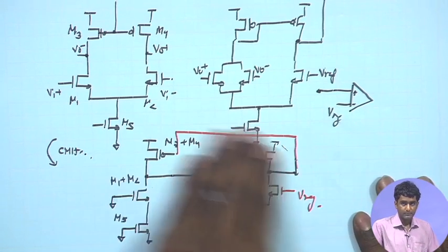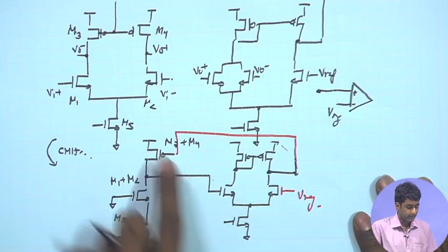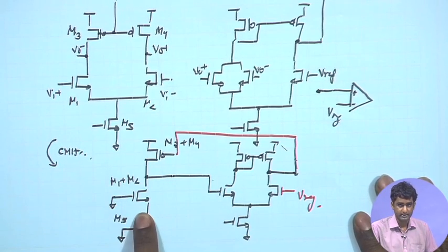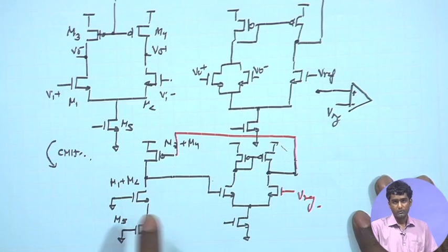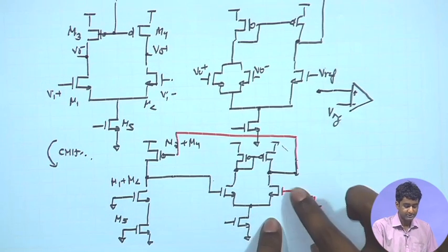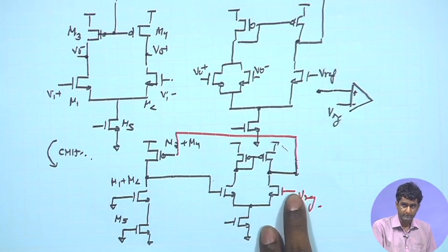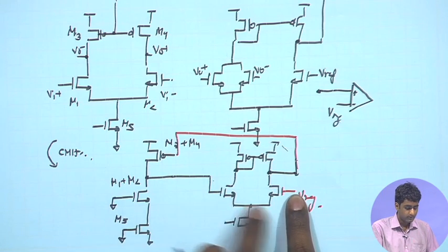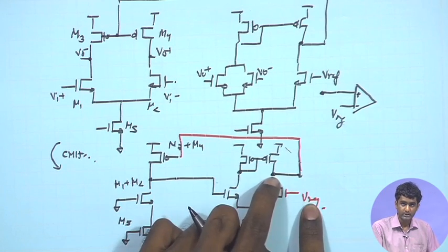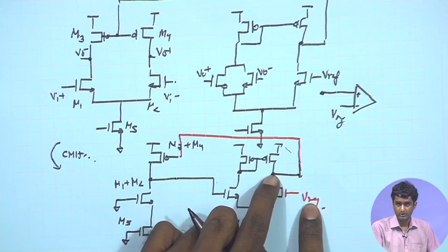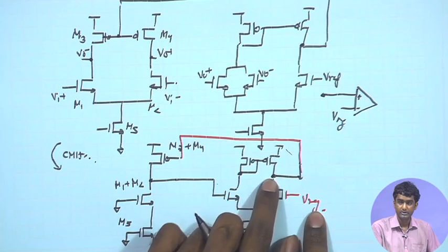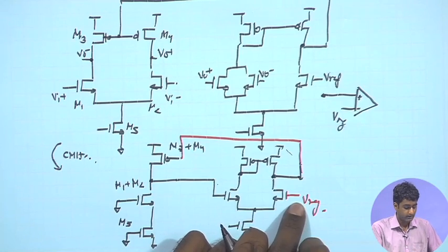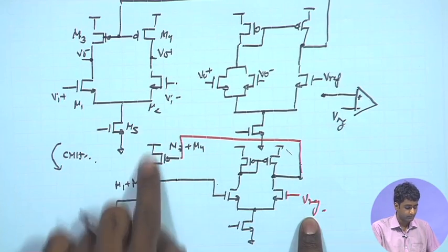But now for this feedback analysis, we have another stage added over here if you look at it. So, this is basically an inverting stage. So, if we break the loop considering the input signal to be the Vref and see how the signal is propagated through the loop, we will see that with respect to Vref, this one is a negative output definitely, because if you increase the Vref, this reduces the inverting terminal with respect to Vref. But after that you have another inverting stage.